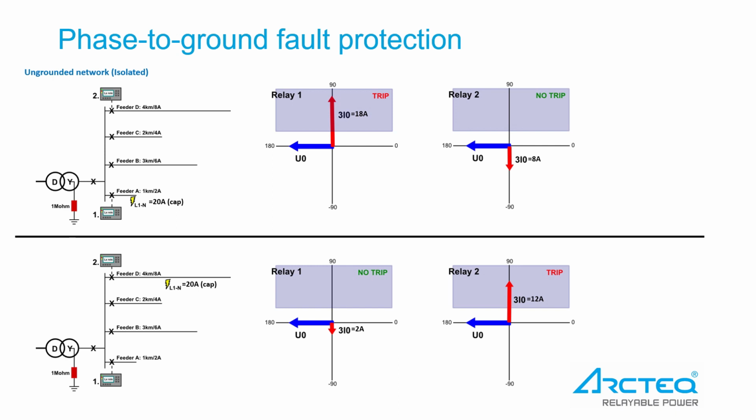In an ungrounded network, a faulty phase touching the ground directly or through resistance has no passage to circulate to the star point of the transformer. In a direct phase to ground fault, the voltage of the network changes dramatically. The voltage of the faulty phase may drop to almost nothing, and the remaining two healthy phases can increase up to line-to-line voltage level.